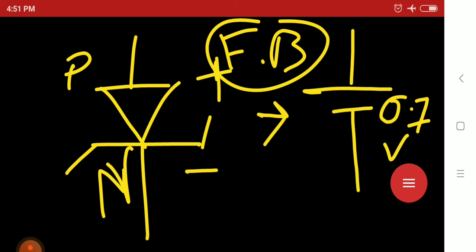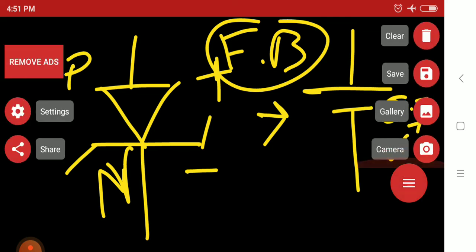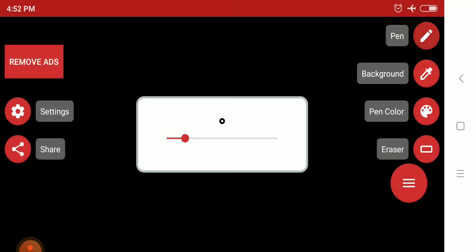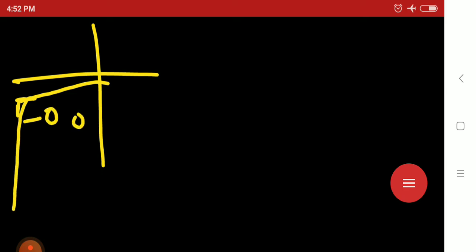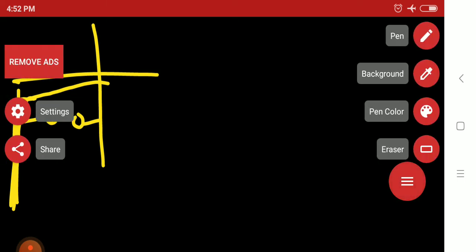Whenever you give reverse bias voltage, first recap that graph. Up to the breakdown voltage, the graph acts as a broken wire. In general, in reverse bias the Zener diode acts as a broken wire. After the breakdown voltage is crossed, a sharp current increases.